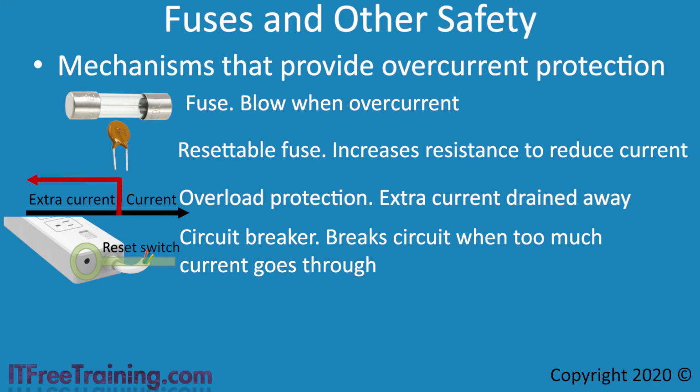Consider that a power strip effectively splits electricity up between multiple devices. If you have devices that require a lot of current, they don't use less. They draw more current through the power strip. All the current is combined together into a single plug connecting the power strip. Therefore, all the current across all the devices is being added together and going through a single point, which is the wall socket. This is why it is not a good idea to plug multiple power strips together.